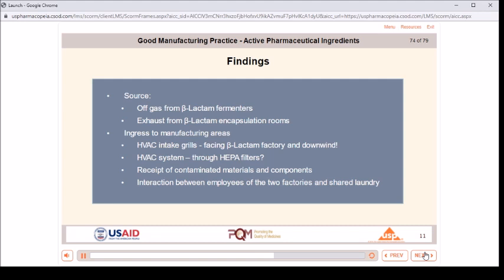It cannot be assumed that because there are HEPA filters, nothing can get through them. HEPA filters are rated based on removing a high percentage of particles above a certain size. They are not rated for particles below that size, and if there are a sufficient number of particles of the size for which they are rated, a small proportion of those particles will penetrate.